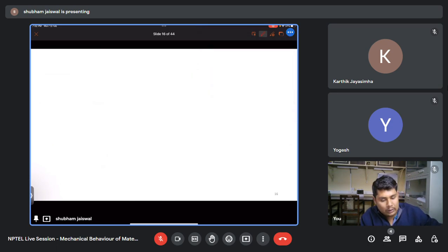I will get epsilon equal to ln(1 plus engineering strain). So as our engineering strain tends to 0, our true strain epsilon tends to that engineering strain. We have made one comment on this, that the true strain is additive in nature. So have you understood that concept?